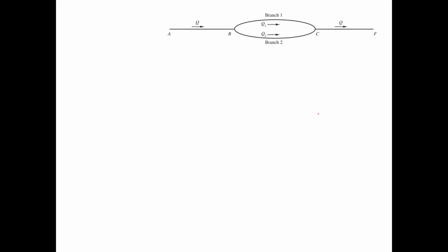I have the picture. I will write whatever I have. It says Q is 100 cubic meter per second. I don't have the information, so if I have them wrong here, let me know. L1, 500 meter, D1, 2 meter, F1, 0.08. This is a type of question that you will see in the exam. Probably I may change that and say that you should find F from Moody diagram.